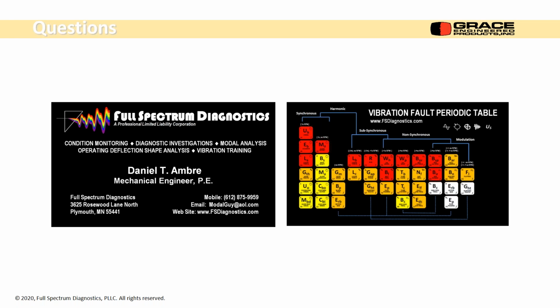It can. A lot of times, if you're on a wireless transducer, you're going to be taking data all the time. So the VFD is likely moving with the process and changing your shaft speed. The real problem is being consistent with your data collection. Now you're moving your shaft speed all over the place and it's changing the overall response, but eventually you'll get a handle on that. You can also go in the plant PI system and try to see where you're changing speed.